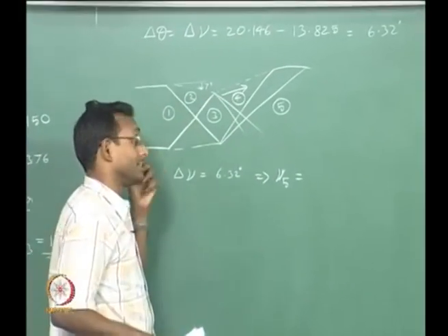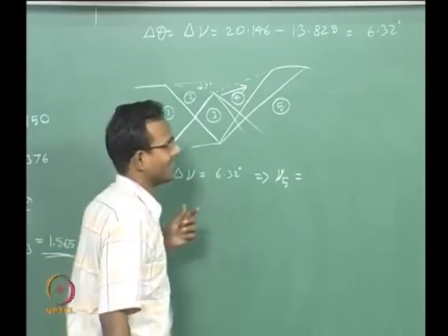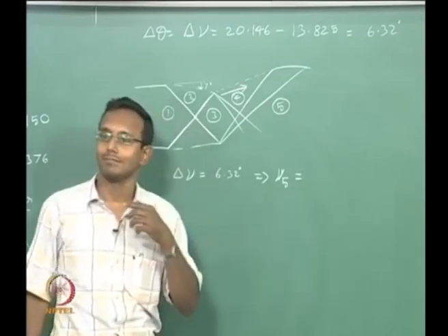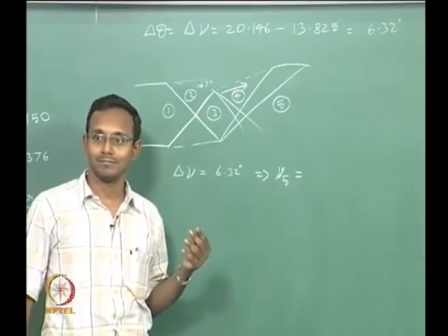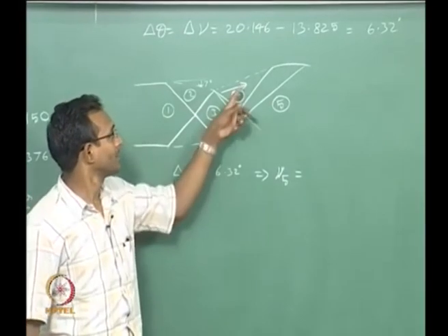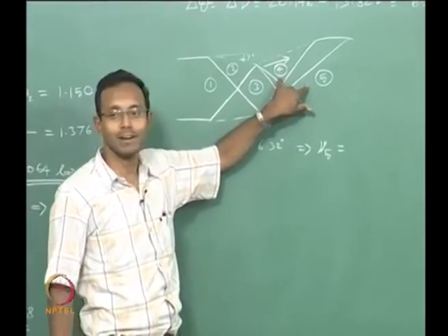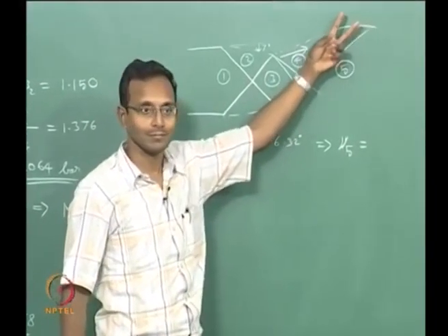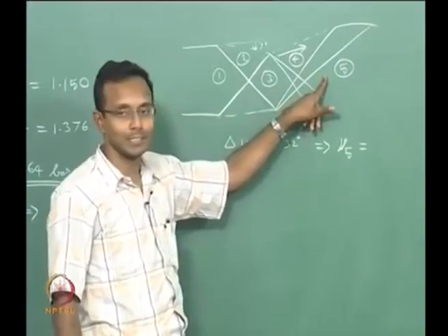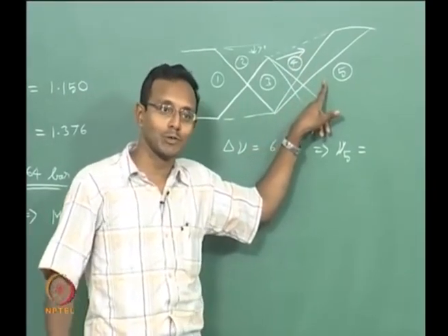should it increase or decrease nu from 4 to 5? Nu will decrease. Why? I am going to ask why even if you said increase. Is it compressing from here to here? 4 to 5, it is expanding because it is experiencing this expansion wave. So actually what should happen to my nu?